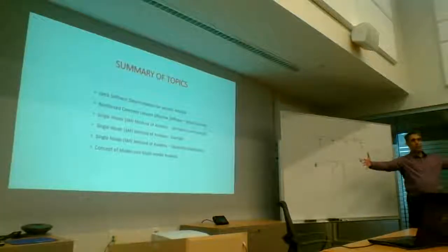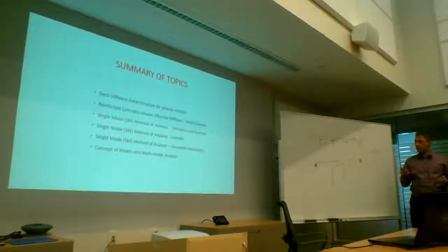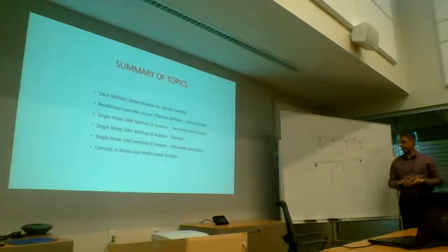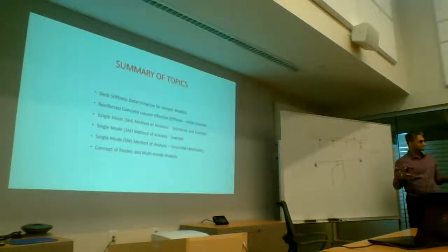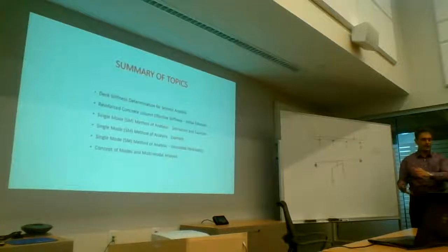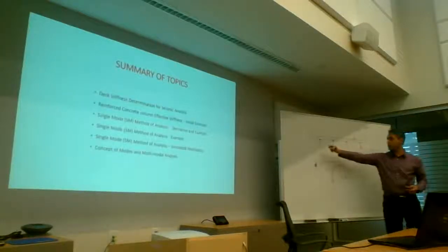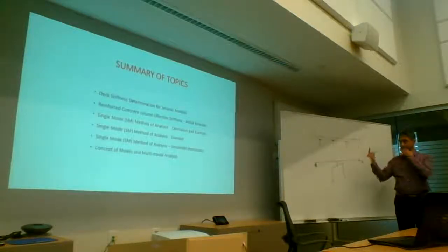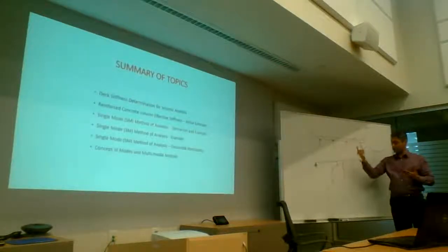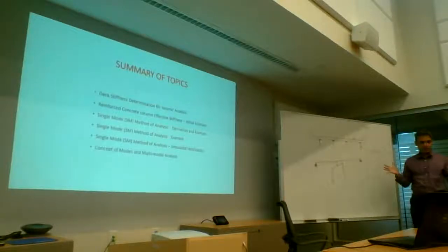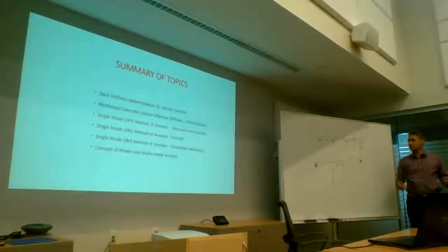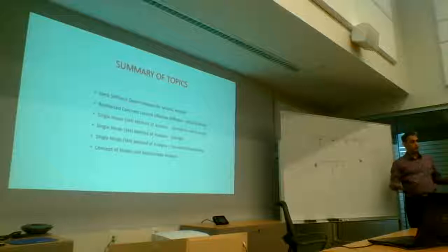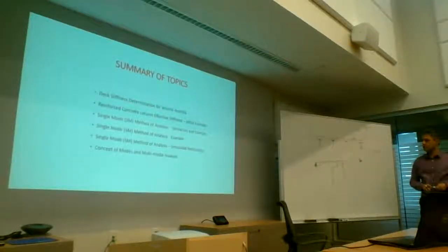When the bridges get really large, then you can start to lose some of the rotational inertia effects, and then you might want to think about having a grillage, which is multiple spines, and so you could run a stick at each one of these girder locations and have some transverse elements to model the deck. Whatever it is, if it is of reasonable width, not too wide, and its aspect ratio is not too large, then you can really just do this.